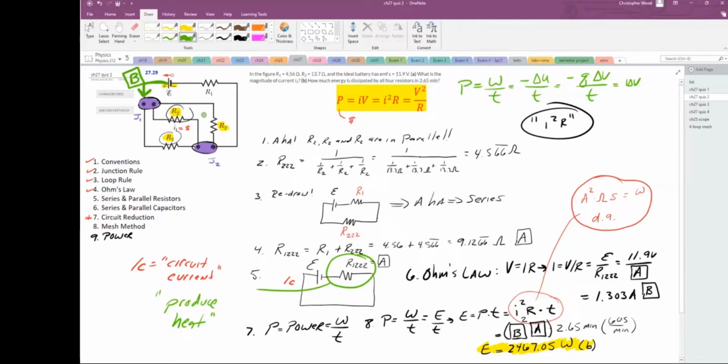And you can see, this is the easy simplified way versus the very heavy lifting way, because I can see I have three equivalent resistors. The current going into junction J1 is going to be split three ways evenly because R2 is the same everywhere. This resistor right here is the same as this resistor, is the same as this resistor. You're going to branch off into three equivalent paths. So this could be one of your pathways, this would be another pathway, I2, and then this would be the third pathway, I3.